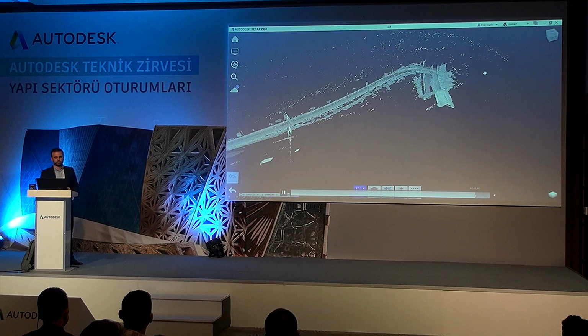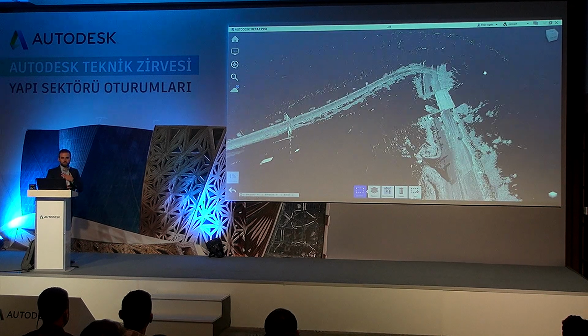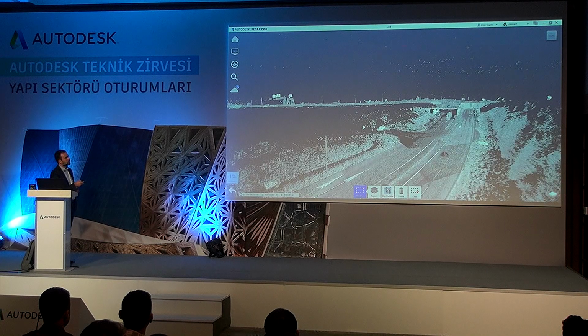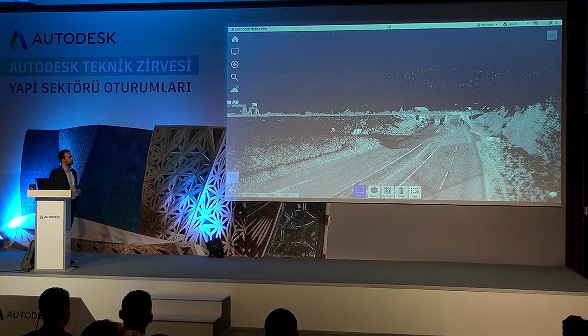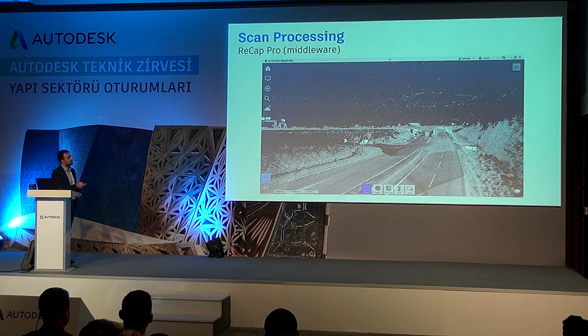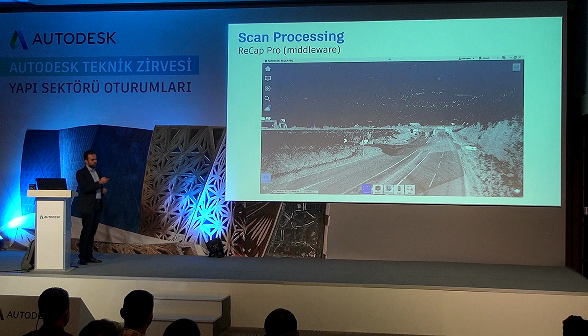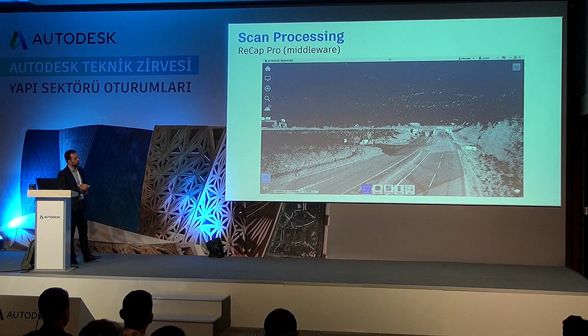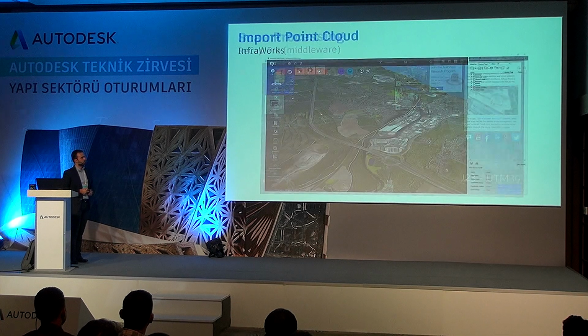So this is very quickly a recap. And definitely if the designer wants to trim or filter some of the noise, you will have some points sitting in the cloud, could be some dust. Maybe there is a dust storm and the laser scanner picked up the dust in the air, because the laser scanner sent a beam, this dust particle reflected it, so it created a point in the model. So we can, inside of Recap, filter out or remove some of the noise in the model very quickly.